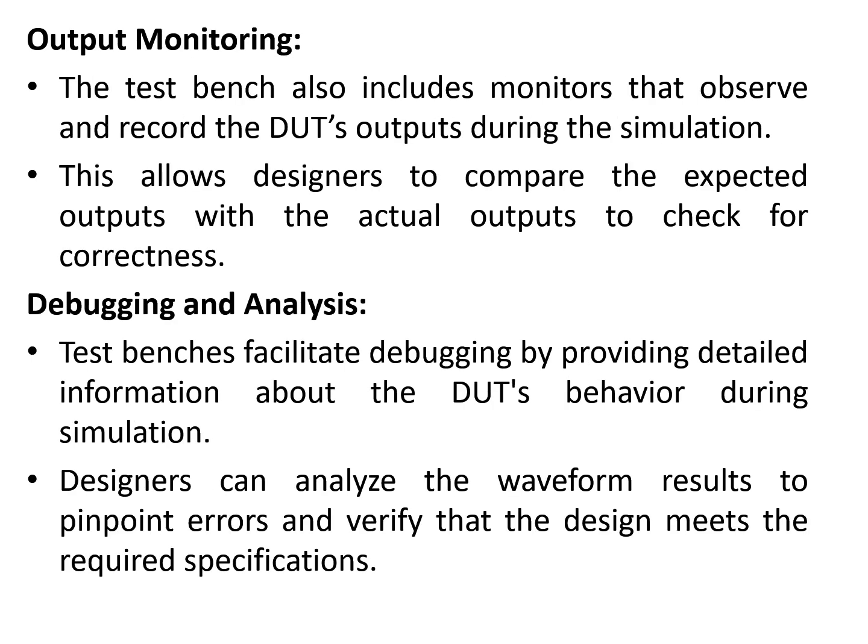Output monitoring. The test bench also includes monitors that can observe and record the design under test output during the simulation. This allows the designers to compare the expected outputs with the actual outputs to check whether the output is correct or not.